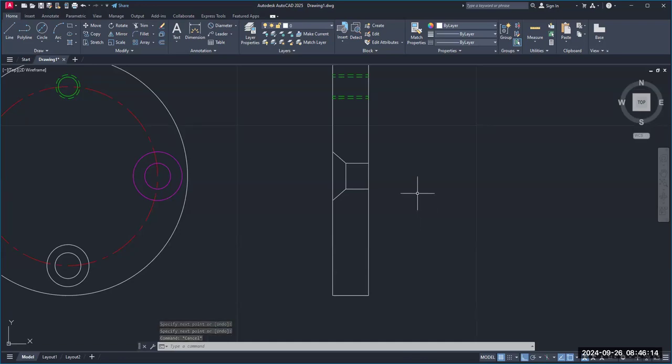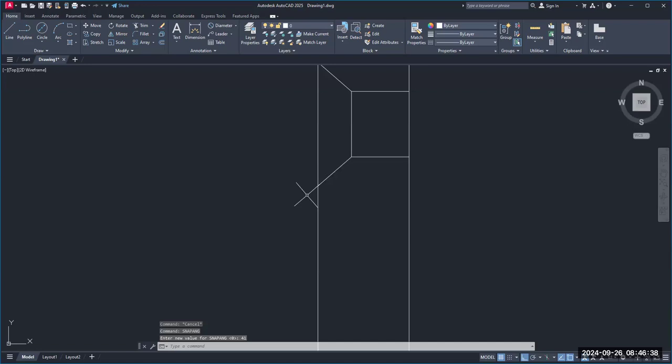Did I go too fast? The snap angles. Yeah, your crosshair should be crooked. Right now, it's at 0 degrees. When I typed in snap angle, look, 41, it gives me this angle here that I can draw that line at that angle.